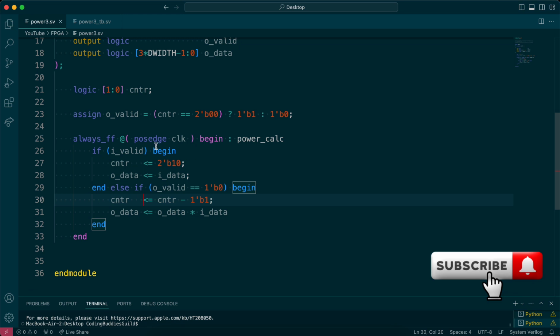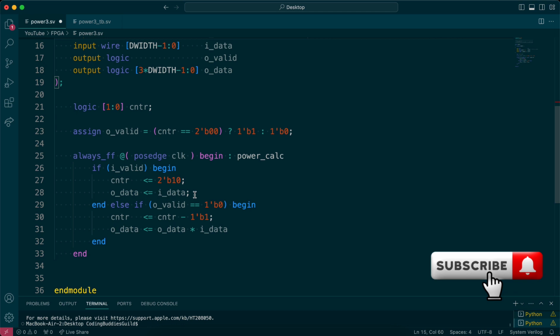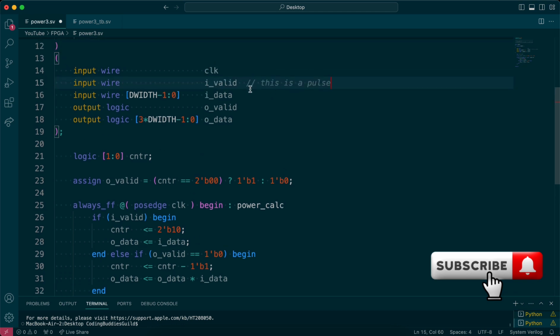What's happening here is that iValid comes in, and I'm just going to add here, this is a pulse. So for 1 clock cycle, it goes up and then it's down. And then when the next input data comes in and it's valid, it goes up again and comes down in the next clock. So it is a pulse. Once I design it, I say, okay, this is my specification. This is how I want my circuit to work.